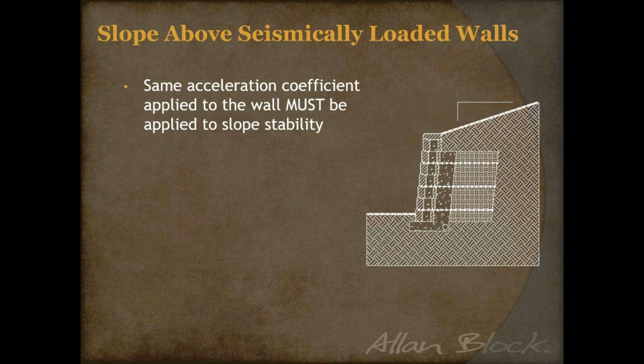But in essence, if you're familiar with soil mechanics, you have your K sub A, because we use Coulomb's earth pressure coefficient. So we calculate our K sub A, and then we multiply that times your depth and unit weight of your soil, and you get that active pressure. Think of it the same way. I've got the height of the wall, but now what we're going to do is calculate a dynamic K sub A. That's going to add additional force to this.